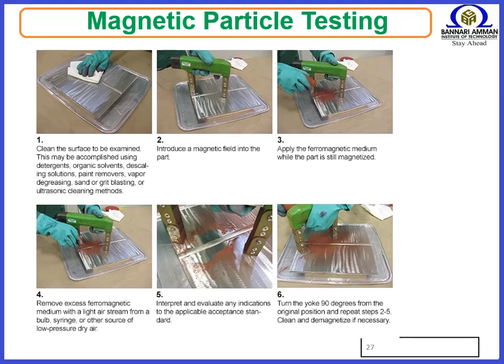Parts inspected by the magnetic particle method may sometimes have an objectionable residual magnetic field that may interfere with subsequent manufacturing operations or service of the component. Possible reasons for demagnetization include: it may interfere with welding and/or machining operations; it can affect gauges that are sensitive to magnetic fields if placed in close proximity; and abrasive particles may adhere to components' surfaces and cause an increase in wear to engines' components, gears, bearings, etc.